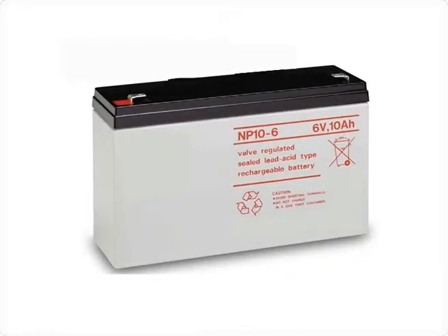The batteries are the reserves built into the UPS. They are the U in the UPS. This alternate source of power keeps your equipment running when the utility power fails. The size and the capacity of the batteries and the current drawn by the UPS load determine how long the UPS will run on the battery power when the main power has failed.